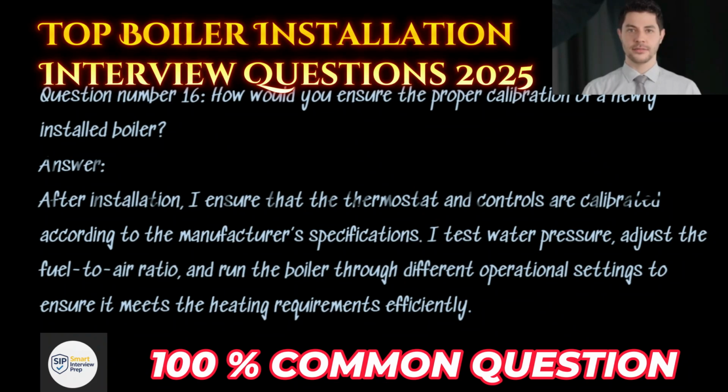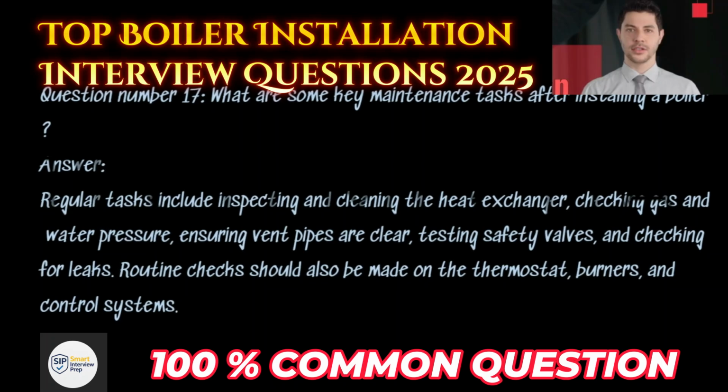Question number 16. How would you ensure the proper calibration of a newly installed boiler? Answer. After installation, I ensure that the thermostat and controls are calibrated according to the manufacturer's specifications. I test water pressure, adjust the fuel-to-air ratio, and run the boiler through different operational settings to ensure it meets the heating requirements sufficiently.